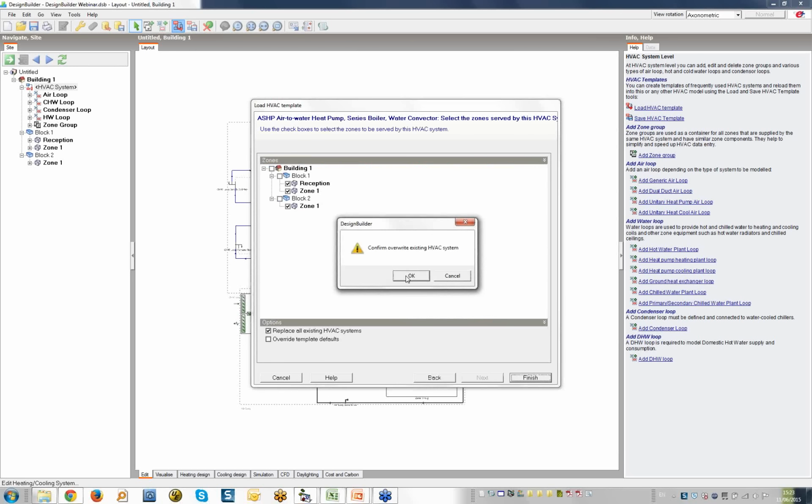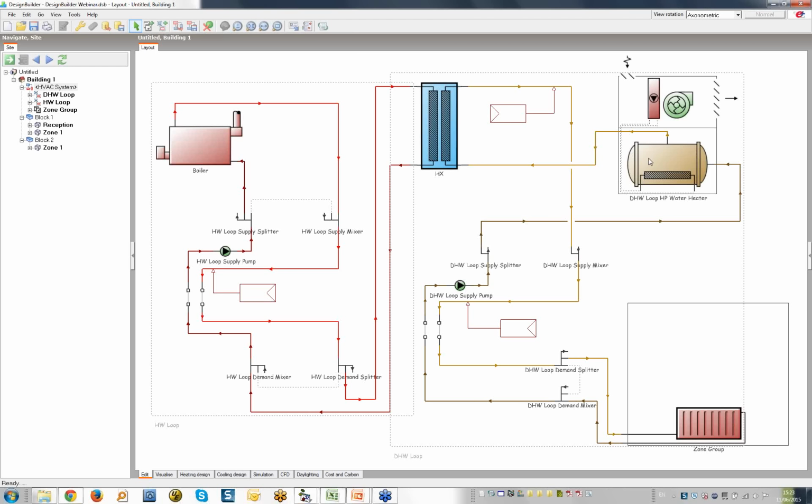The heat pump supplies hot refrigerant to the heat exchanger in the EnergyPlus water heater tank component. This is a typical configuration to prevent cycling of the heat pump and to improve efficiency.